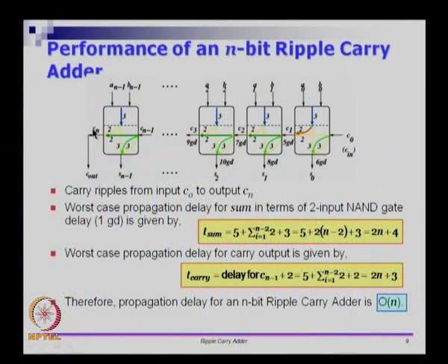So one final thing that I want you to think about is the carry that is coming out here, right, has an interesting property. If I have a 4 bit Ripplecarry adder and let us say I have another 4 bit Ripplecarry adder, I can take the carry out that is coming from one stage and give it as C0 for the next stage, you can make a 8 bit adder out of that, right.